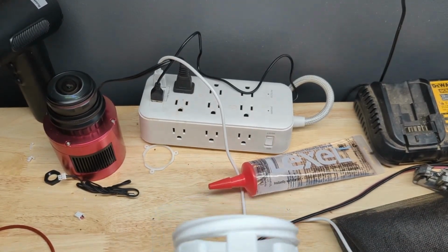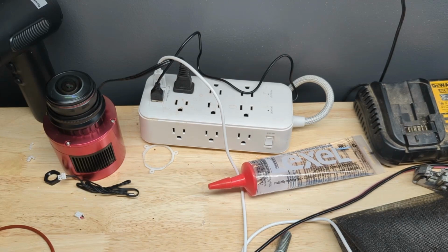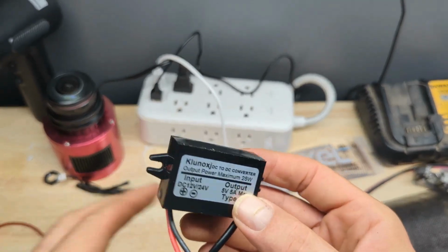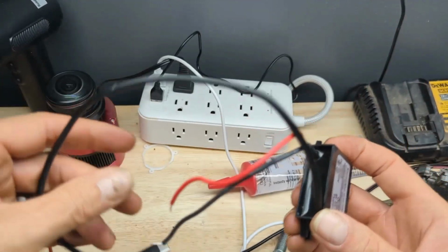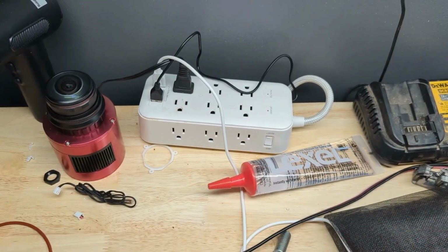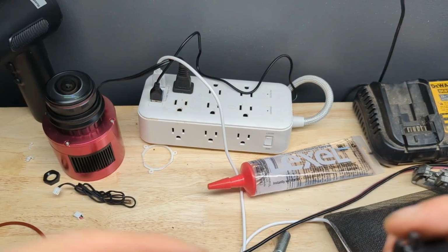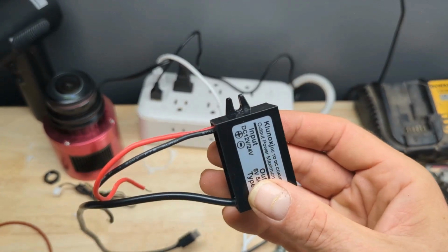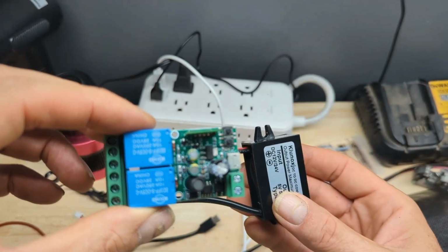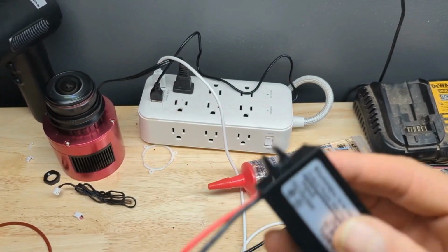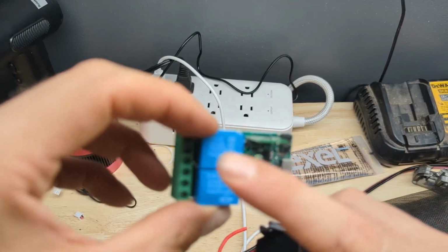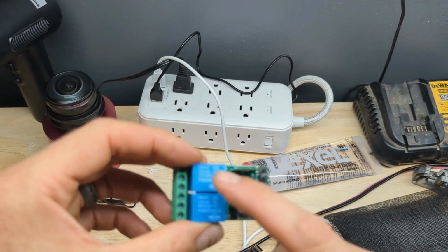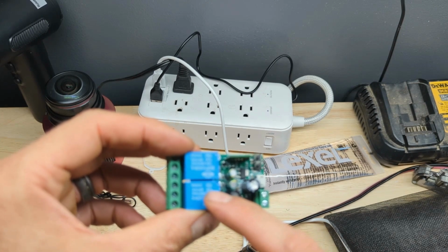We have several options. We still have our Raspberry Pi power module that we need to connect, and that is a USB cable. And of course these wires, they need to be able to somehow get over there. They're actually not going to go to that side. The Raspberry Pi power module is actually going to connect to this module, which is going to be on the same side as it. What we're going to have is the Raspberry Pi will connect to one power module and one power switch, and then the camera will connect to the second one.